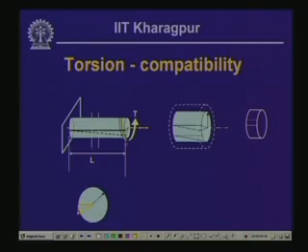As I said, because of the application of this twisting moment, the length which was originally straight forms this helix and thereby there is a change in an angle, which we have called theta. Now, if we cut a segment from this particular length, let us call this length dx, which is designated over here.